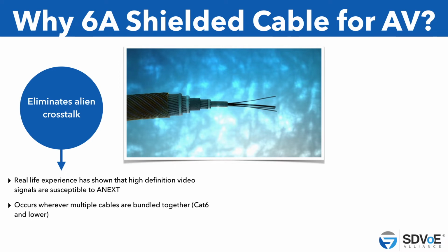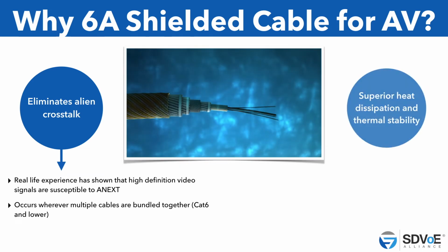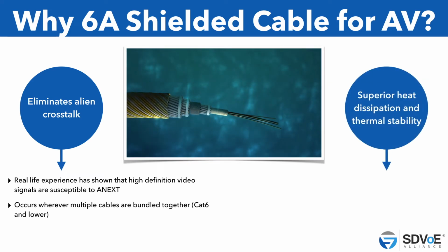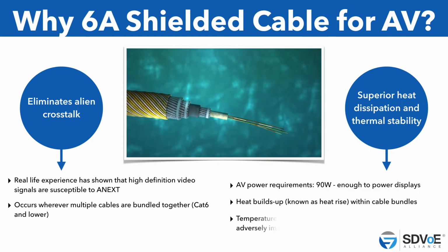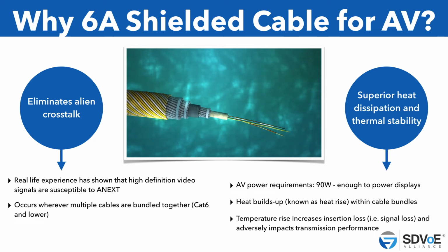Another little thing, when we start talking about technology now, we start talking about things like power over Ethernet. How are we going to get the power to these devices? And with power over Ethernet, if you think about it, if we're delivering 90 watts over a cable, what's going to happen to that cable? Is that cable going to heat up? Well, the reality is if a cable overheats, it will affect the amount of data transmission. So we've done a lot of work trying to maximize the protection within the cable, so we're going to deal with it.